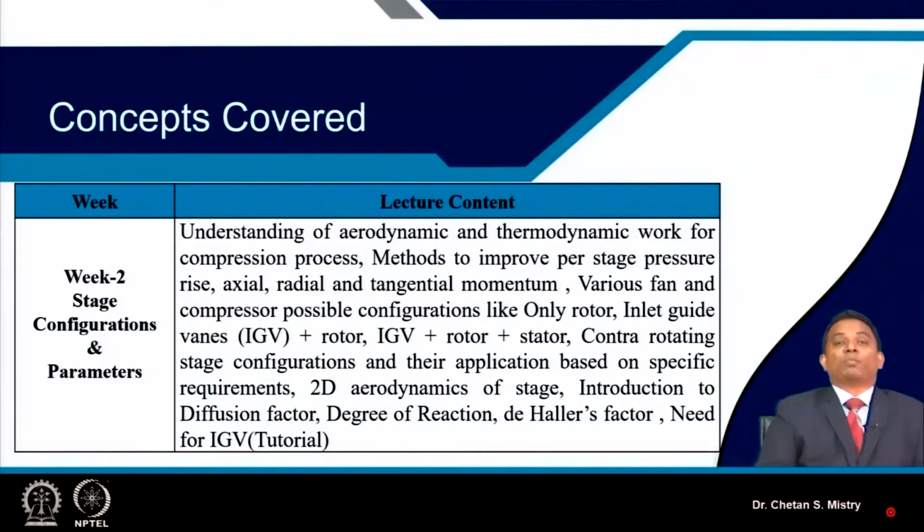Then we introduced the parameter called degree of reaction, and that is an equally important parameter. It gives us an idea whether the diffusion is happening in our rotor, or only in the stator, or in both rotor and stator. Based on that, we will be doing our calculation for design or degree of reaction. We have discussed that it is a thermodynamic measure of your diffusion process.